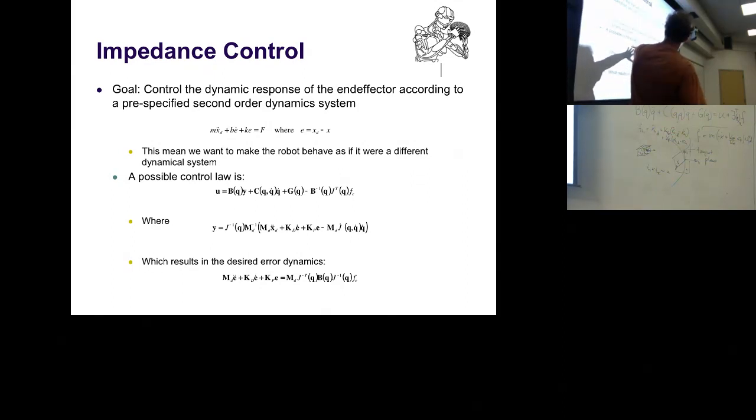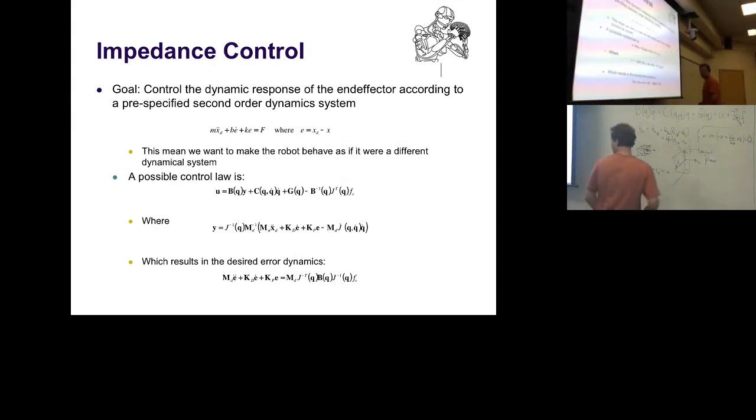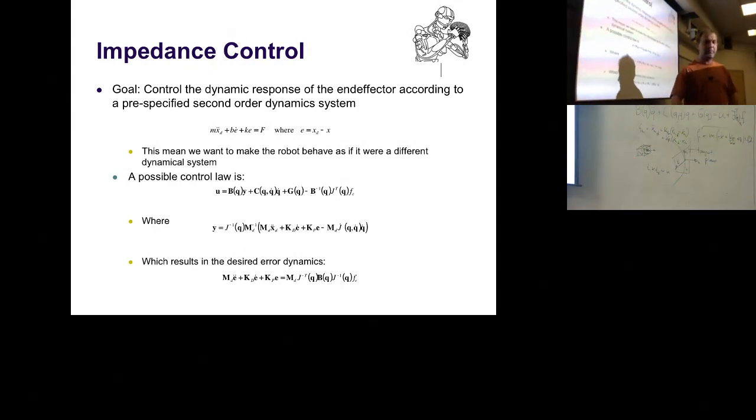You get control laws which look essentially like our normal inverse dynamics control law. You get your Jacobian transpose. You get your FE here. Then you get somehow inverted inertial matrices in there to make sure that you compensate for what is called the anisotropy of the inertia tensor. Nice word. Okay, very simple.